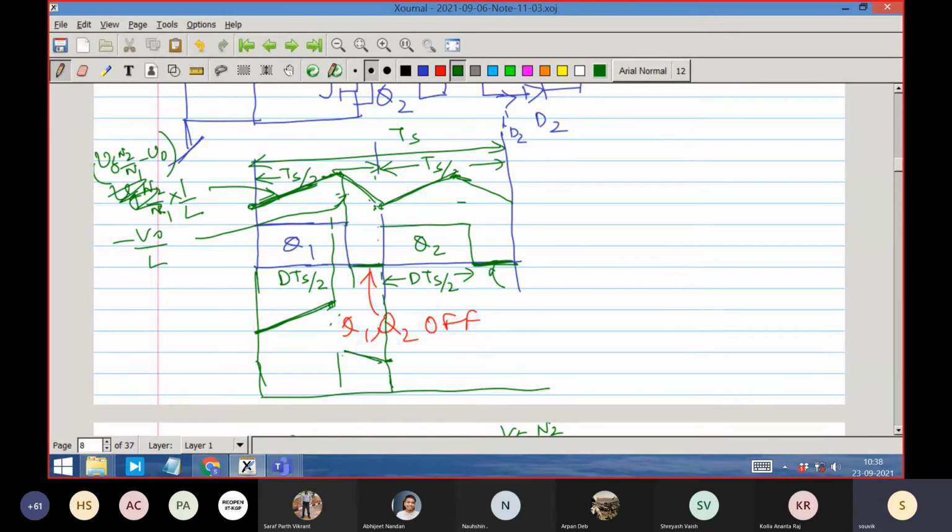Are you happy now? Does the question remain or has the question gone? This is the diode. Yes, sir. It's clear. Then in the subsequent part, it will scale down to half. It will come up as long as Q1 is on, the diode D1 with high current is on. Subsequently, it is conducting in a freewheeling manner, but with half the current, because half the current has gone to D2. This half is now here in D1, half is in D2.